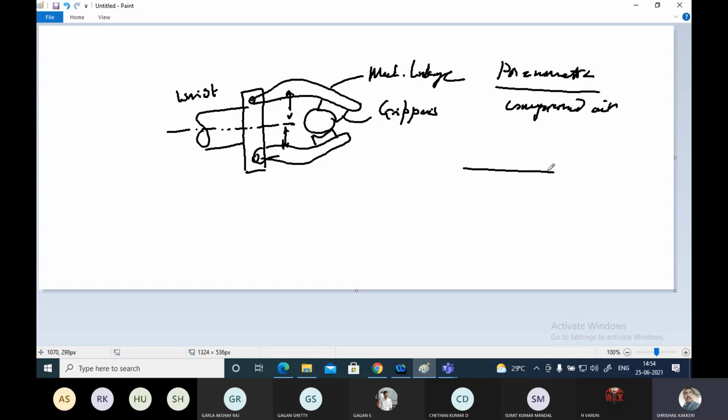How? See, this will be again the end effector of the robot, and this is called a wrist. And at the end of this, there will be a pneumatic cylinder fixed. And this pneumatic cylinder will be having the pistons, and these pistons will be having the vacuum cup. Vacuum cups will be there, and we are going to put the input and output.